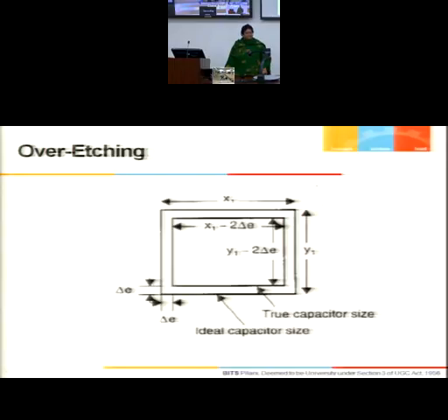Now if I make a bigger transistor by using many small unit transistors, even if there is etching, the ratio I want is 2. I was using a bigger transistor of W 20 and length 10. Now suppose I use small components, 2 by 1 or 4 by 2.